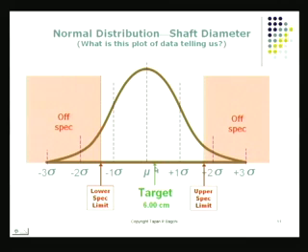So I show the target here with a green arrow there. The process average should ideally be exactly right there. That's something we'd like to be able to do. Now that's the midpoint of the specification range. The second thing we'd also like to do is not see as much variation as is shown on this graph. Rather, we should have a sigma that is fairly tight and stays pretty close to that midpoint there. That way we'll be getting accurate production and also precise production.